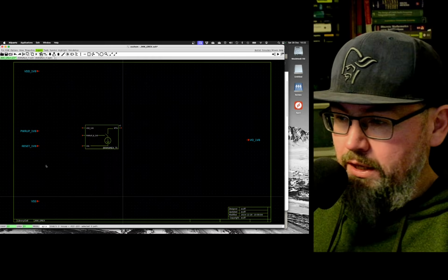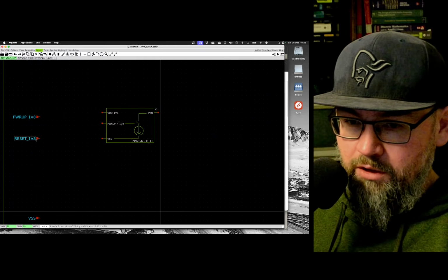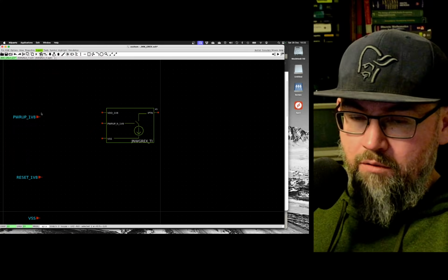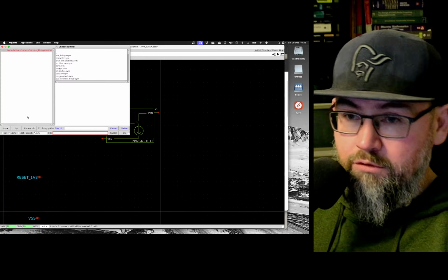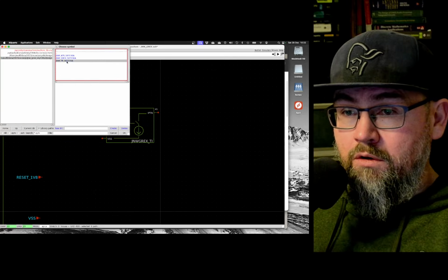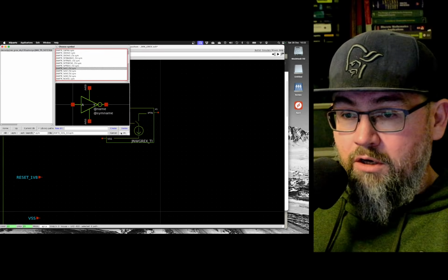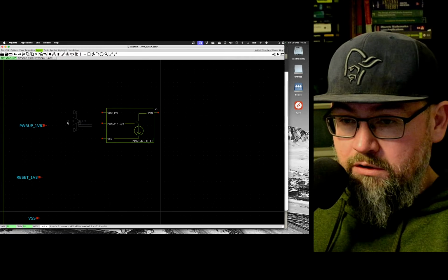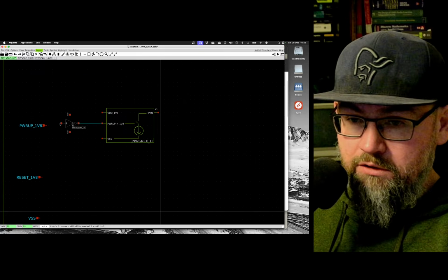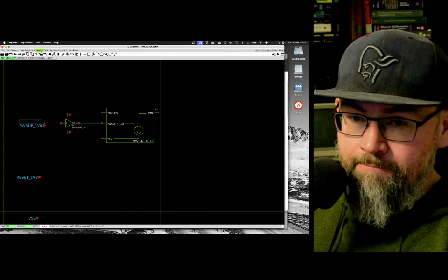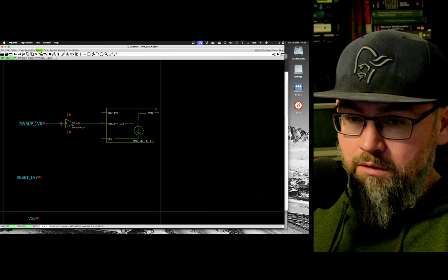It's to give you a very quick understanding of the circuit. Okay, so here we have power up N. We need then the inverted. So let's find an inverter. It's going to be in the transistor library. It's called IVX. We don't need this particular size. It doesn't need to be particularly quick. It just needs to invert. Like that. And then there.